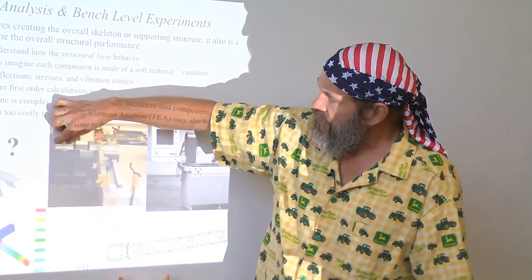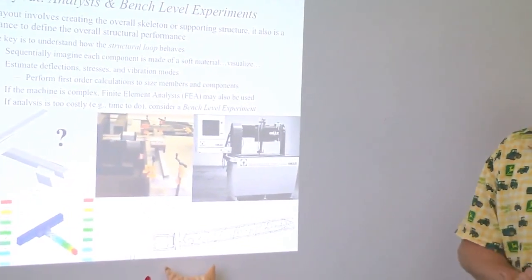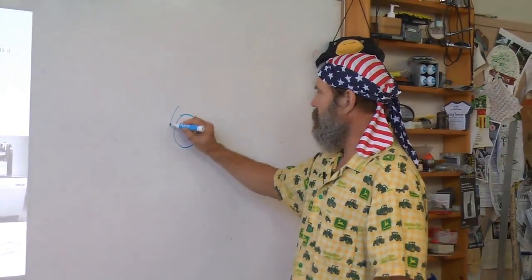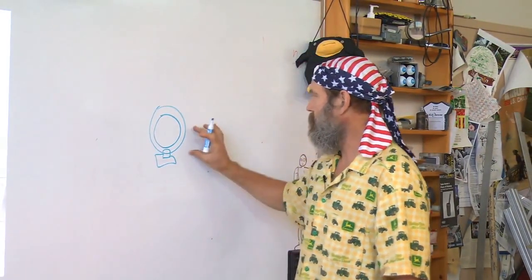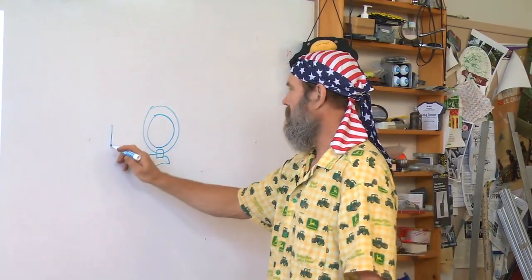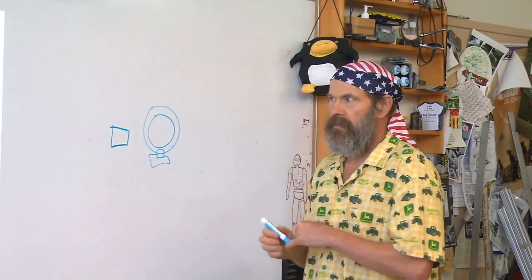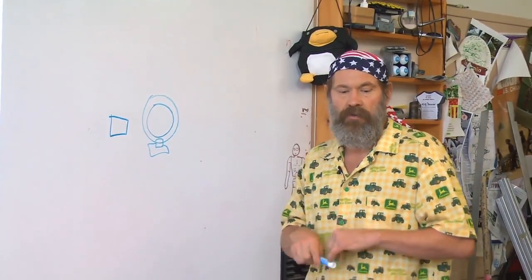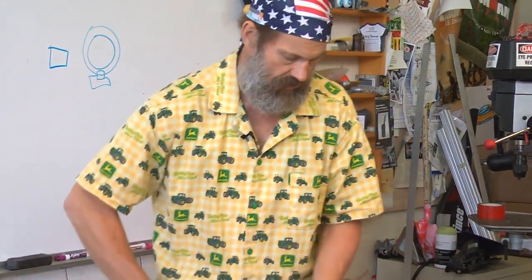The size of this steel rail, see this solid steel rail, becomes just too big. It can't compete with having an aluminum tube with a smaller steel rail and bearing. This was just much stronger in the end, and lower cost, than just putting a bigger and bigger steel rail. The lesson, however, was not lost, that for smaller machines, you can often think about just using the rail itself as the axis.